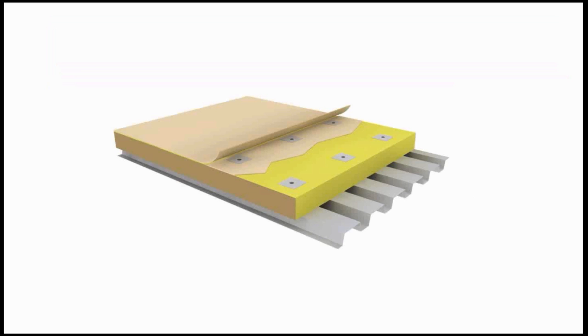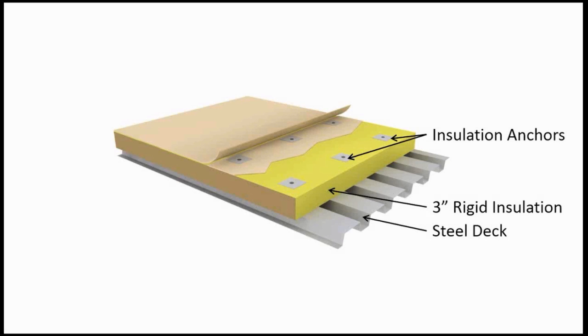So this is the roof system: steel deck, rigid insulation, mechanically fastened. Again, I'm not talking about thermal shorts in general, but we did have a little bit of condensation on the end of the screws, but that typically did not occur. 90% of the time we had dripping. It was not related to the thermal bridge created by the anchors, although that is not a good practice as well. Then there were the membrane anchors, which, because the membrane sheets were 12 feet wide, were at 12 feet on center.